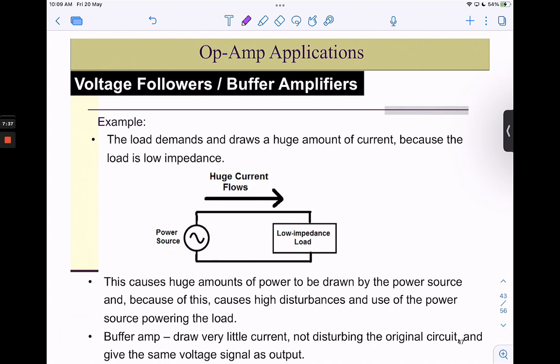So usually the measurement circuit has a lower impedance level as compared to the impedance level of our skin. So a loading effect will occur in the measurement. Okay, so that's why we use a buffer.